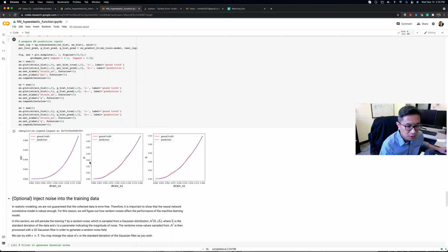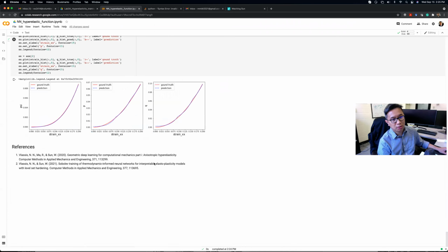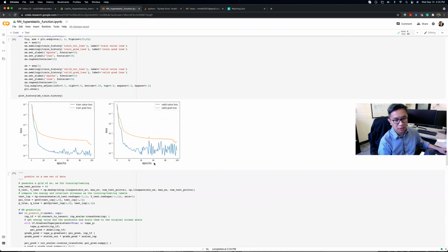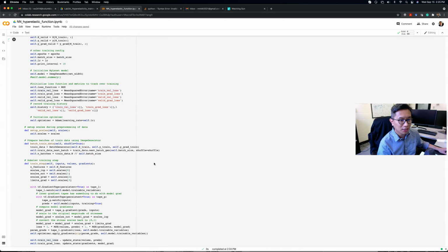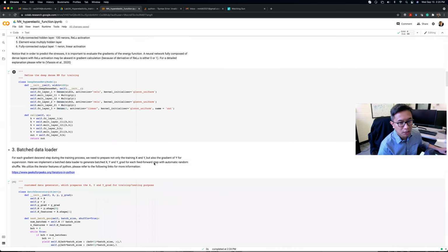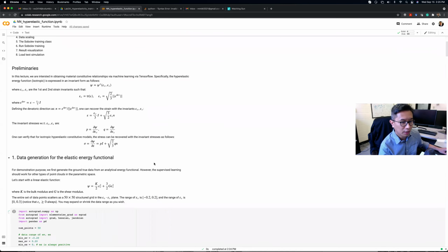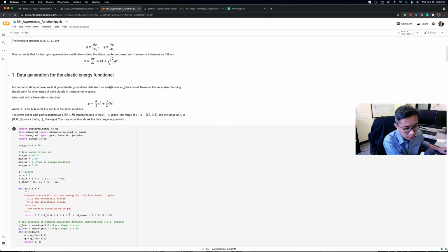But you can also see that the mean stress and the deviatoric stress are now nonlinear. So basically in that script, you can train any isotropic energy functional. I can guarantee that it cannot train any anisotropic energy functional, because you cannot represent anything anisotropic with two invariants. I think that is obvious.